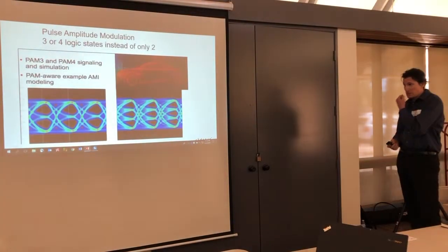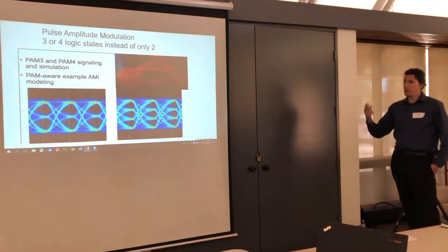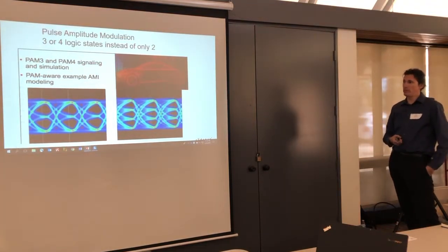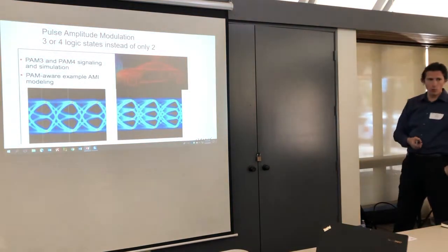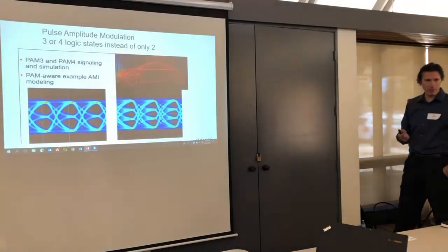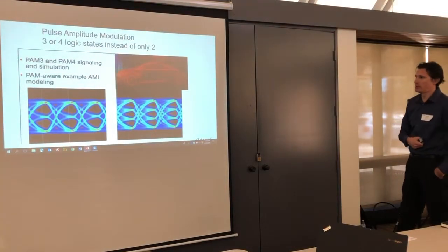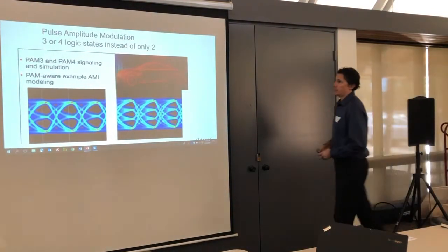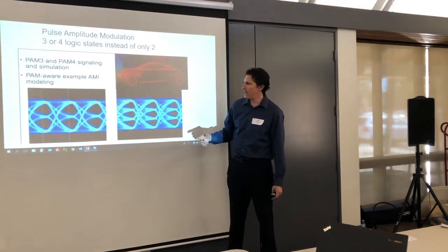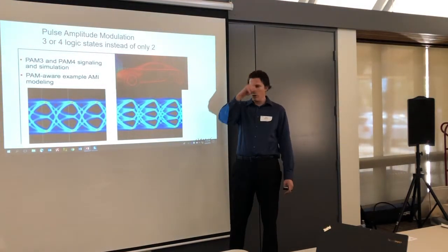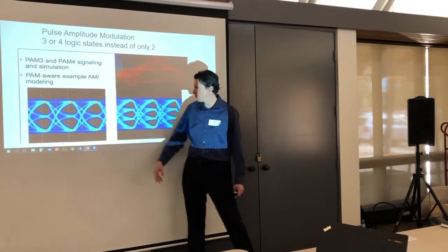So, kind of throw out some other cool keywords out there. Someday some of you may hear somebody saying, oh, we're doing PAM3 or PAM4. So, 0 and 1, that wasn't good enough for people. People needed to cram even more data down some of these high-speed SerDes lines. So, what this basically stands for is pulse amplitude modulation. And the idea with that is instead of a single 0 or 1, you now have multiple logic levels: 1, 2, 3, or 4.